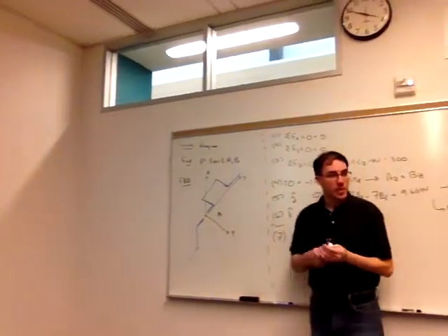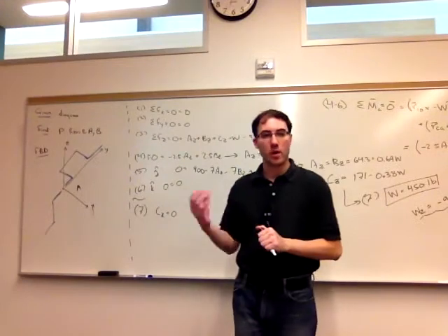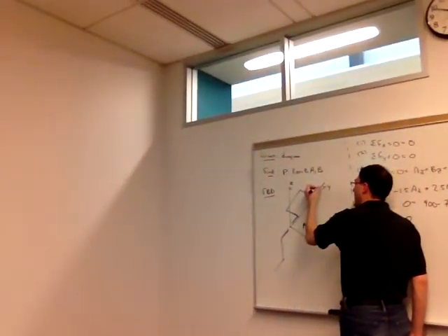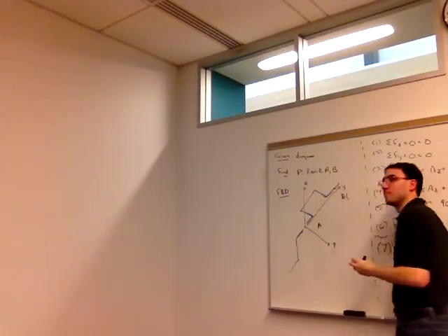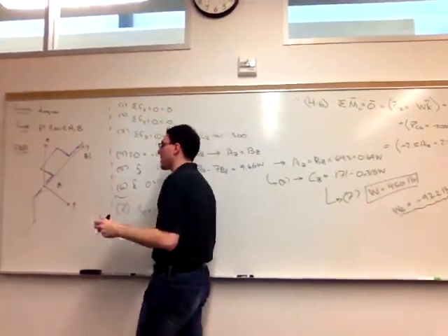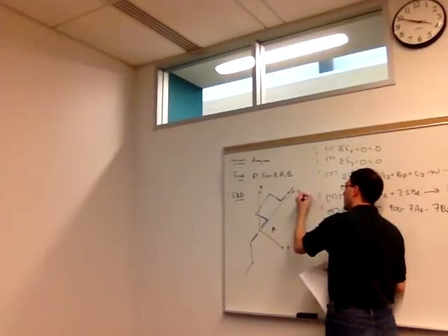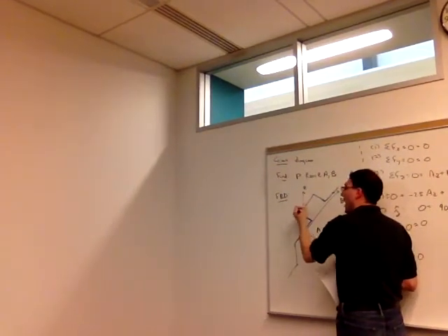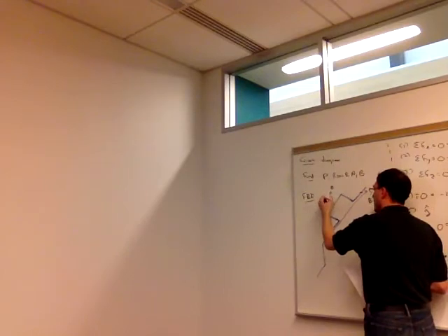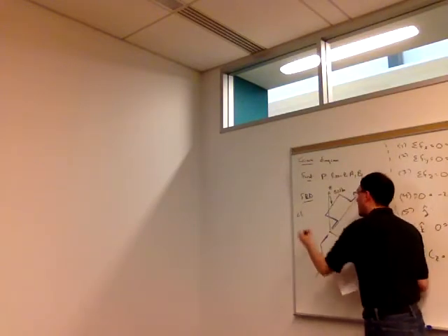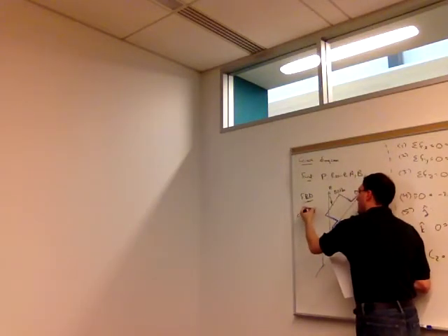So the point A is already on here. That's going to be the origin and also a bearing, so we'll fill that in a minute. It passes through that other bearing at B that we'll have to model. So B is going to be located at 0, 280, 0 inches. We have that applied force of 80 pounds acting at a point that I'll call C, which is at -10, -14, 0.